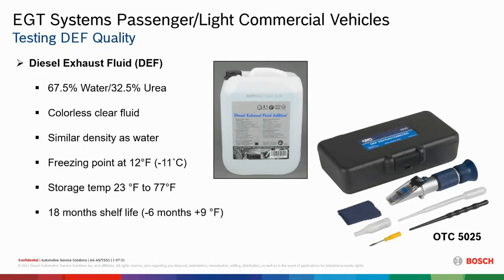One manufacturer that we dealt with in the passenger car side told their technicians if it came in with a DEF quality code, drain the fluid, replace the fluid, clear the code, send the car down the road. If it comes back, obviously, then there's other problems. But most of the time, it can be a quality code that they had. And that was probably preliminary quality sensors, but now it can give a little bit more information to the system.